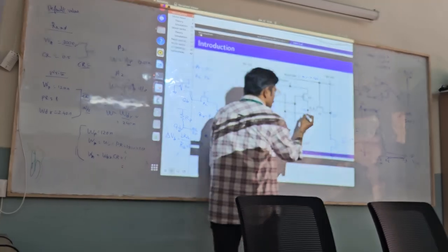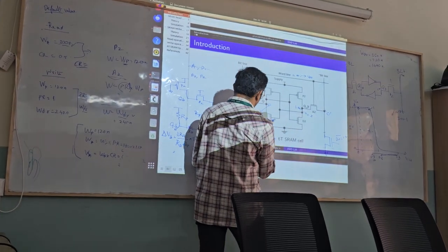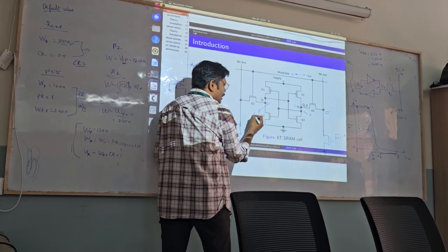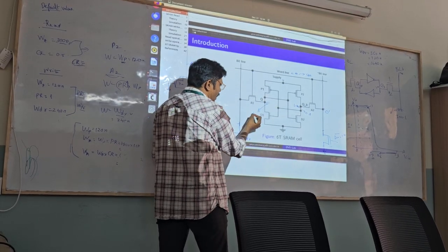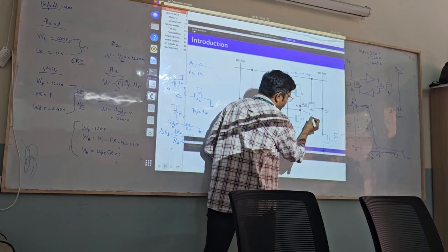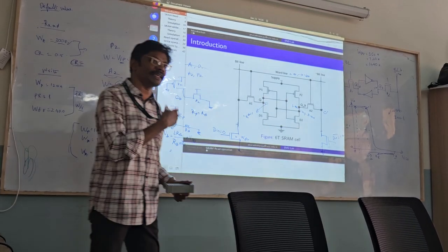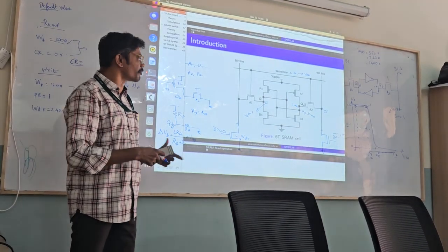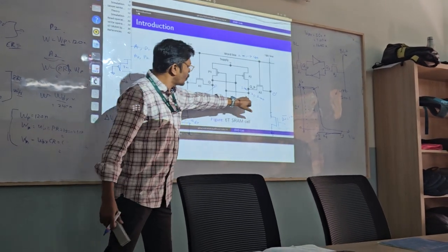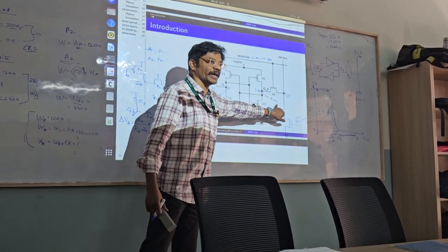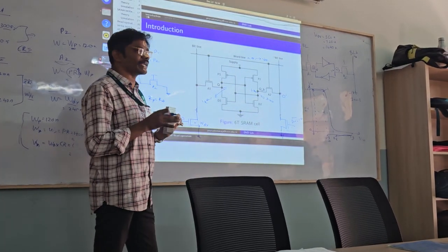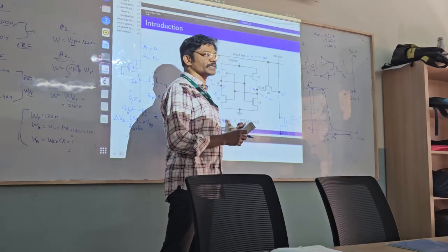Okay? So having this one, bringing from 0 to 1, it goes through this loop, and that in turn will push to 1.2, and that in turn will push this 0.3 to 0 volt. Automatically the circuit will perform some regenerative action to pull this one from 1 volt to 1.2, while the other end goes from 0.3 to 0. The circuit will perform by itself. So the only thing is you have to give enough push to perform this operation.